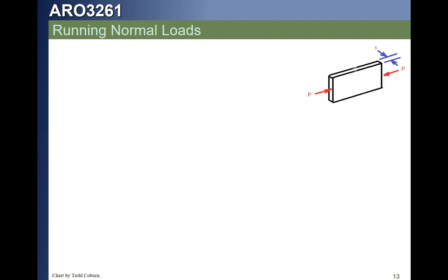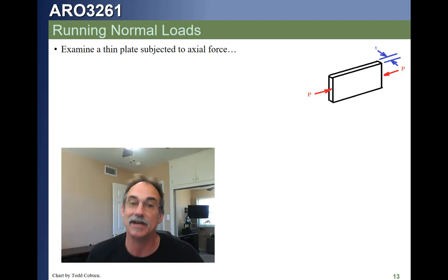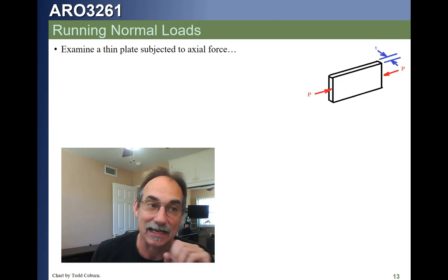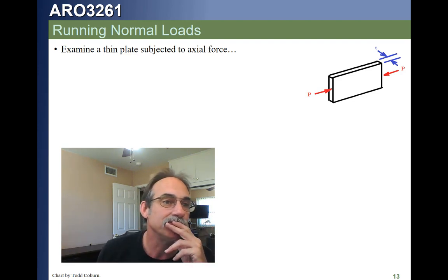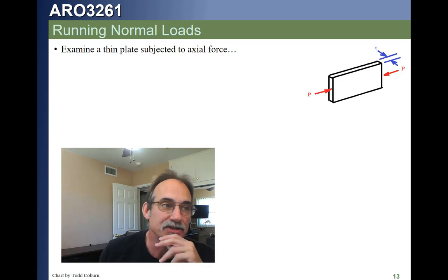Okay. We're going to introduce a new concept, and this is the idea of running loads. This is usually not covered at the undergraduate level, but I heard you folks were wanting to be aerospace engineers, and if you want to be an aerospace engineer, you really need to understand how to calculate running loads. Now, running load is just the force per unit inch.